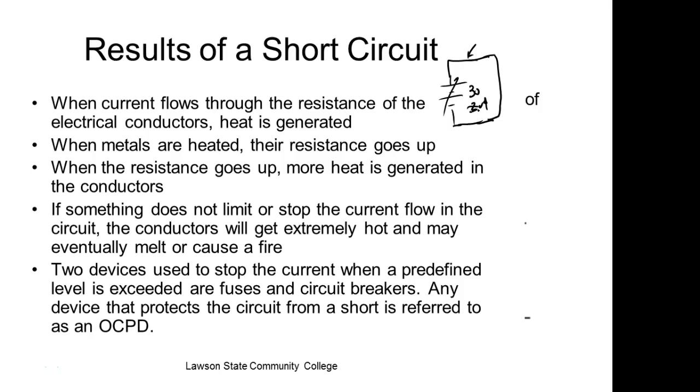Well, this is the problem you have with these extension cords. You run them all over the place. You don't use the right gauge wire. You just use these little thin wires, right, because they're cheap. You go out here to Dollar Tree and buy one for $2. They use very small gauge wire. Then you run it somewhere and you hook your vacuum cleaner up there, 100 watt, 200 watt vacuum cleaner. And what happens? The wires get hot.